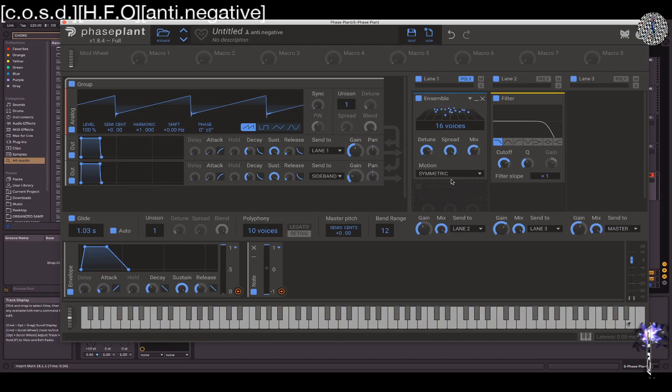This is all stuff we're going to be doing in oscilloscope art class, if you want to go to that. So these are actual vector mapped points and all that stuff, and you can draw all this stuff with it and add modulators in the form of waveforms that create all these different shapes by default. So if you put a sine wave into it, it'll literally create a circle. Put a square wave, it'll look like a square. It takes on the shape of its own waveform input. It's really cool.